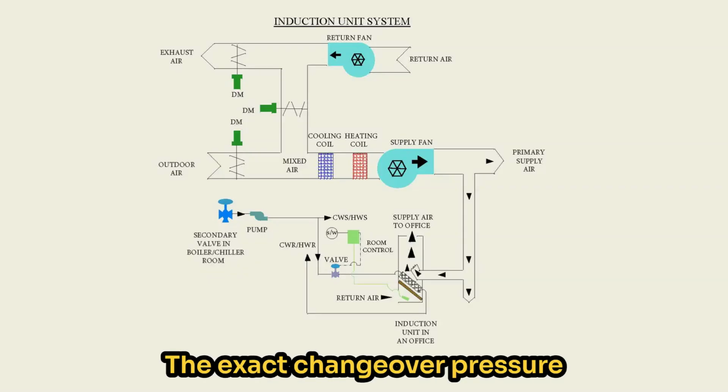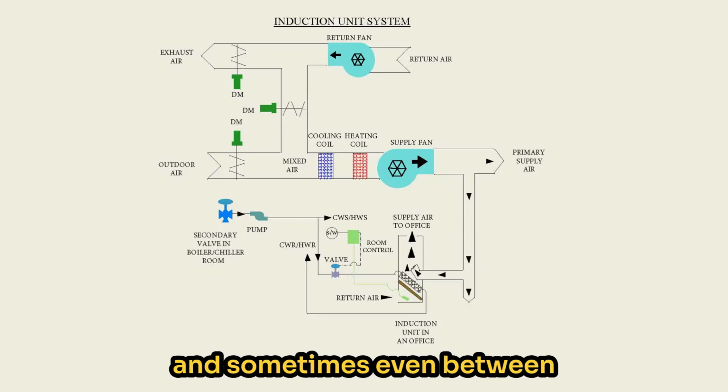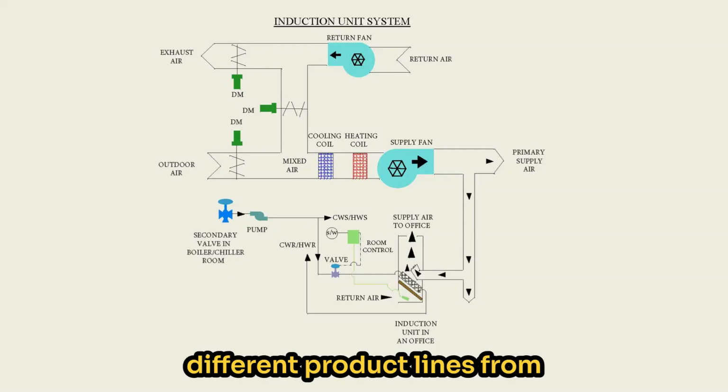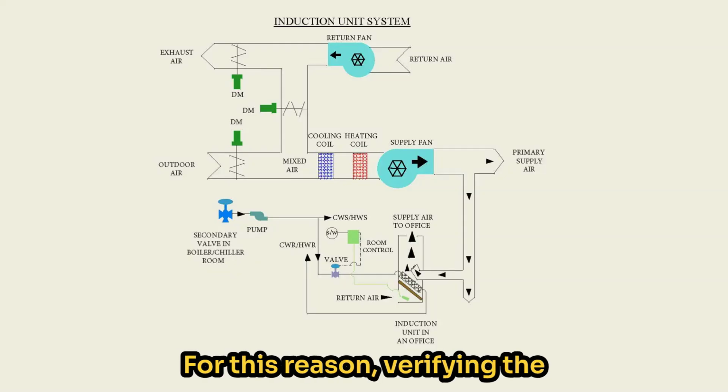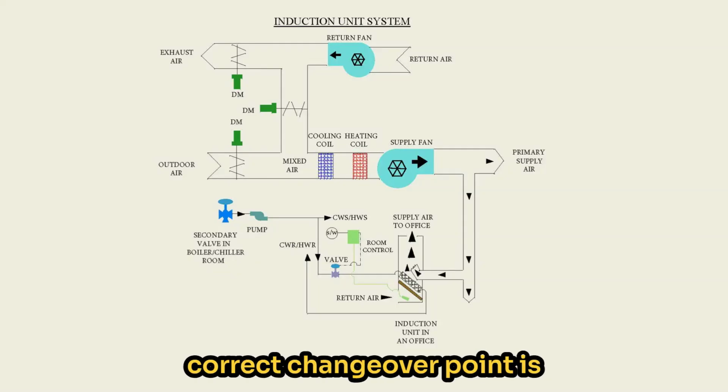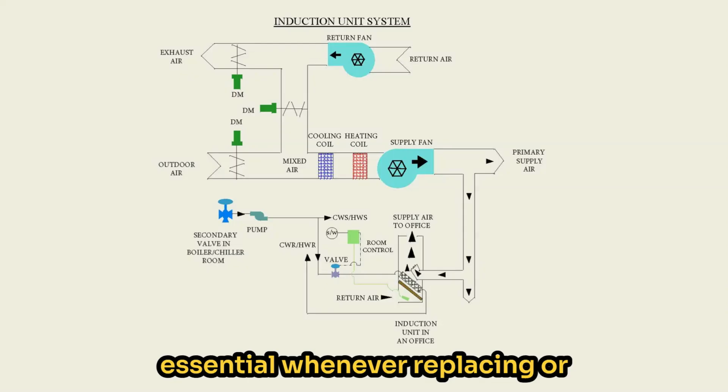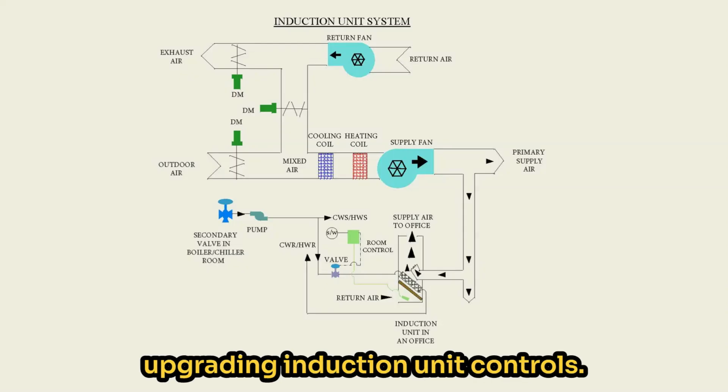The exact changeover pressure varies between manufacturers and sometimes even between different product lines from the same manufacturer. For this reason, verifying the correct changeover point is essential whenever replacing or upgrading induction unit controls.